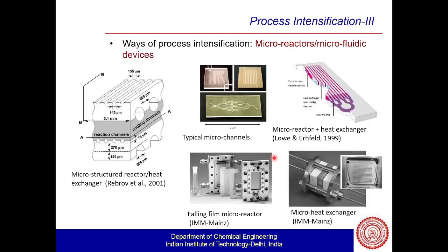And going to that of the microfluidic reactors or the microfluidic devices. So typically here we decrease the channel width itself so that the surface forces actually come into play. They are more dominant in this region, and therefore by manipulating the surface forces, since I decrease the size of the channel, which is of the micron level in case of microreactor, the specific surface area increases. And the specific surface area increase actually causes the enhancement of the heat and the mass transfer.